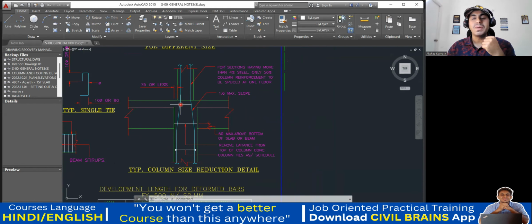In some cases, let us say it is a 4-story building, G plus 4. Up to the 3rd floor, you give a column size of, let us say, 230 by 450. But in the terrace portion, you might feel that much size is not required. So instead of 230 by 450, you go with 230 by 300. So almost a 150 reduction in size has been done. Simple. That is what he's trying to tell us.